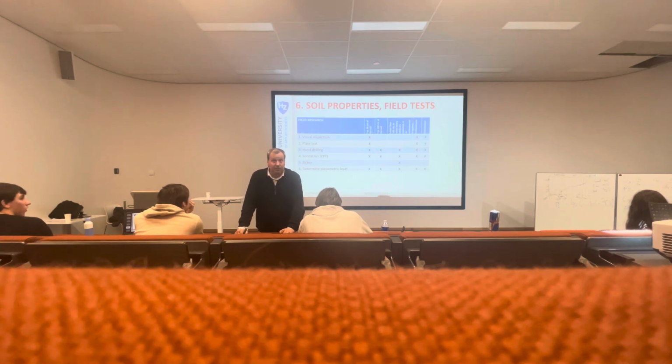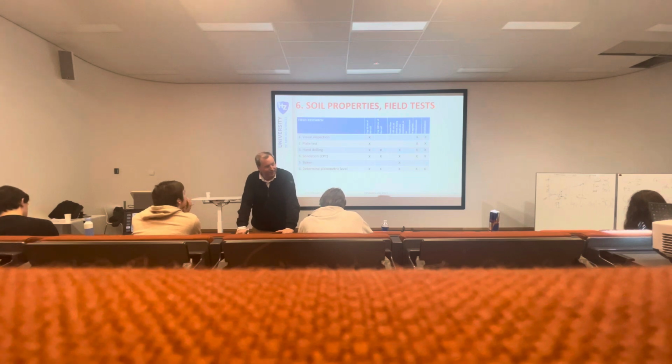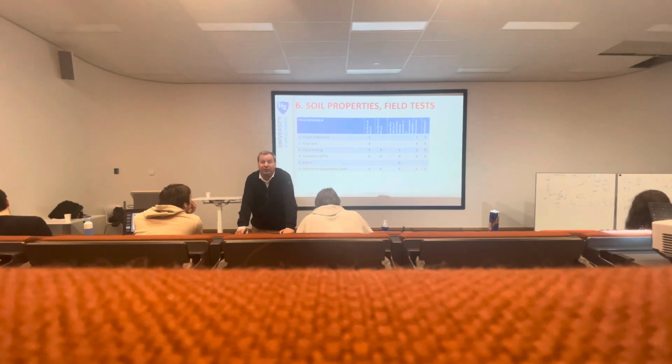Vegetation can say something. If you are in the desert, what do you see there? Cactus. That's a nice desert that you have. Most of the time, not that much, not that good. And when you have more green and types of trees, then you can also see where the groundwater level is. When it's green in a dry period, then we know what type of soil we have. When it's a dry period and it still looks green, it's clay, exactly, because you have a high capillarity, all for free, without having to dig something. You can directly see, okay, this is this type of soil.